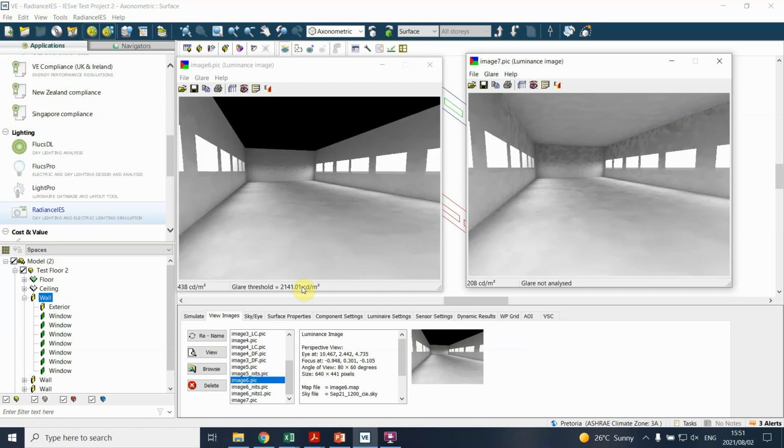So when you've got a very dark space with a light source with a high level of light, you've got a continuous discomfort or a reflection taking place. We call the one disability glare. That's what we experience when we drive at night or when you walk around at night and it's dark and there's a light source. Then often you struggle to manage with it because you're either momentarily looking at the light source and you're blind, or you're looking at the darkness but then you're missing the light source. So it's difficult to manage both at once.